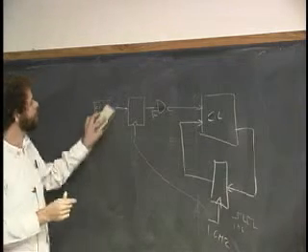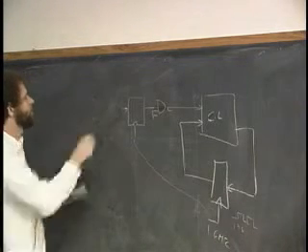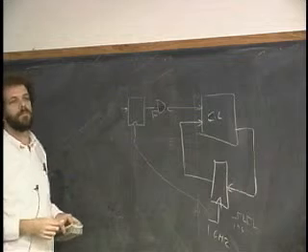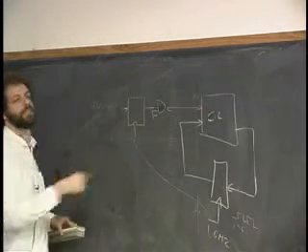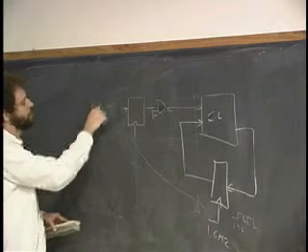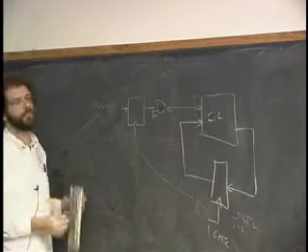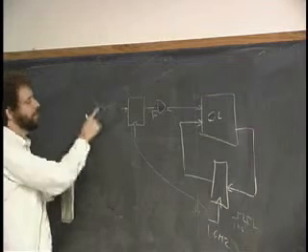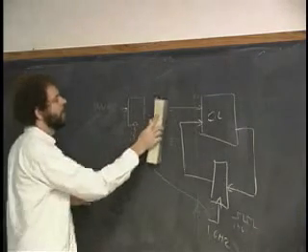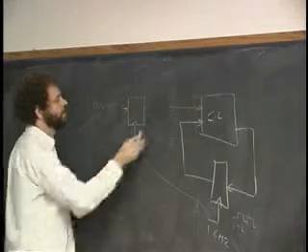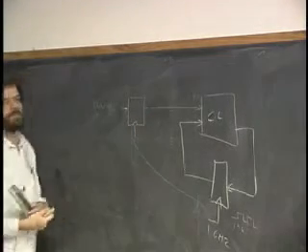But let's say that this isn't the Coke button, and we're actually getting a whole bunch of data in here. In fact, let's say that we're getting data that's changing almost as fast as the clock. Let's say it's changing every 4 clock cycles. How are we going to deal with it? How do we synchronize this data to that clock? So we can't wait around and not look at the output for that long. Other ideas?